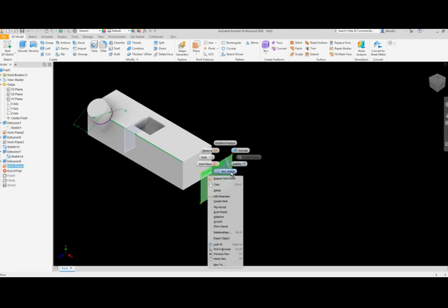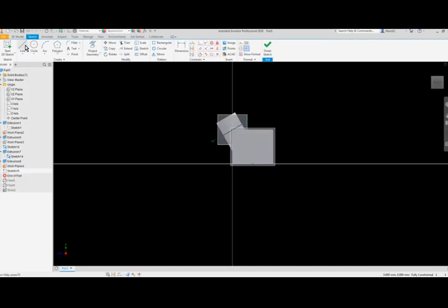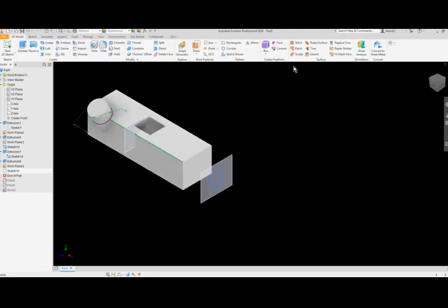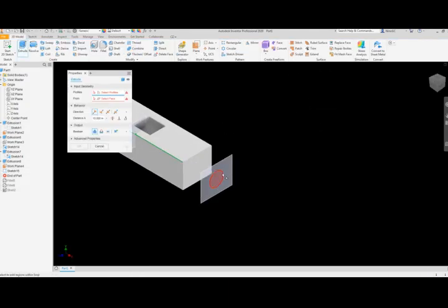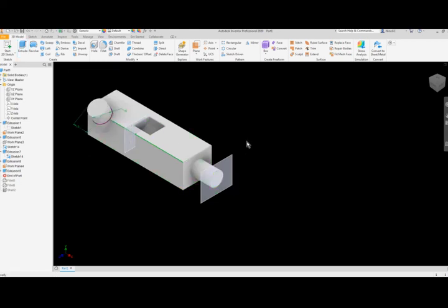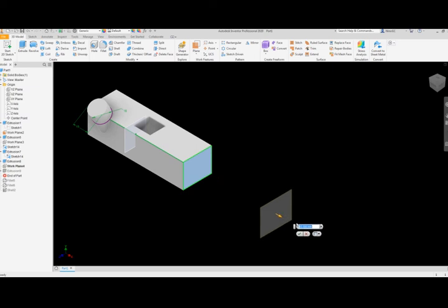I'm going to create a new sketch on it, and I'm going to create just a circle. I'll do a random circle like that. I will select the circle and say go to next. Click OK. Now, if I change where that work plane is located, for example, if I drag it all the way here to, say, 82, that feature will also be attached, simply because it starts from here and it's looking for its next surface.